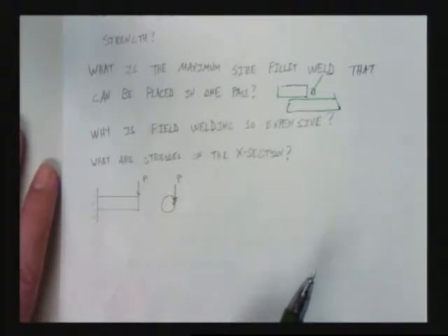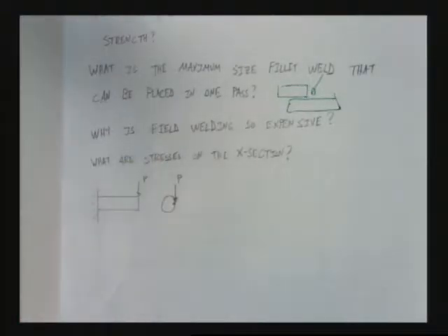It's like a paper clip going back and forth, back and forth, back and forth. Eventually the paper clip's going to break, if you're moving it large enough. If you keep those deformations small, it won't break. You put a nick in the paper clip, it's going to break even faster. That's what we're talking about with these imperfections.